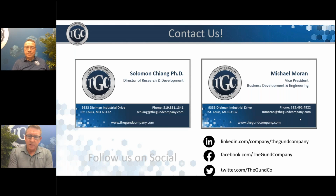So let's see, we've got a couple more here that we can work off of. How about this one? I think you covered this a little bit, but from Kevin, he says, how many test samples are required when doing thermal aging? You are required at each cycle a minimum of 5. Okay. For statistics, I think that's like every UL test they do a minimum of 5. Okay, very good. Let's see if we've got anybody raising their hand.